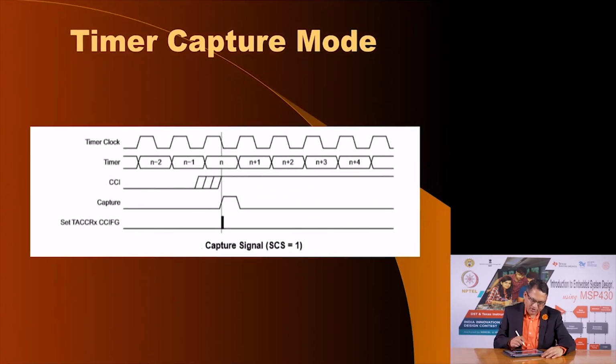Now, this is what happens. Your timer clock, whatever be the source, you are going to capture the value into the capture register whenever the appropriate condition arrives. It will capture the value here of the timer into the selected register.